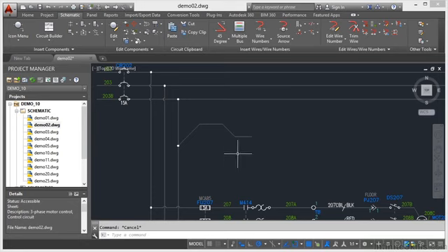I don't have to think about any of this because it's all linked to my AutoCAD electrical project and those symbols, those little connector blocks in the project settings and the drawing settings. So because I'm using a default AutoCAD electrical Demo 10 project, all of those settings are already in there for me. So I don't need to worry about that. They're all there ready for me to use. So that's how you insert your wires at different angles. So let's try that one more time.